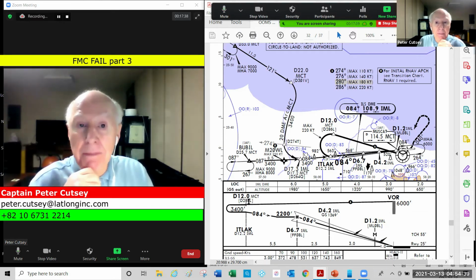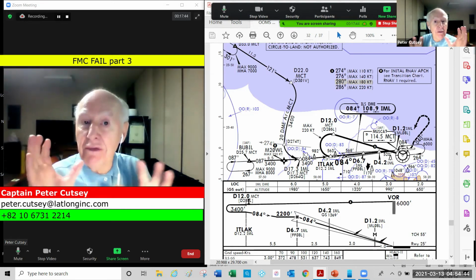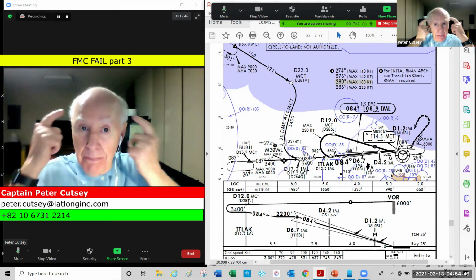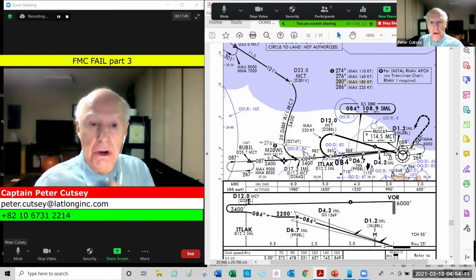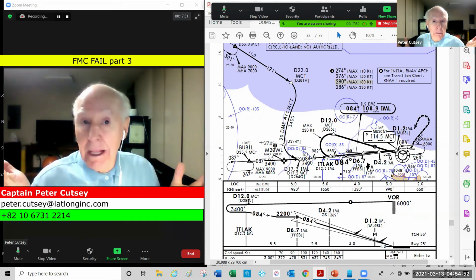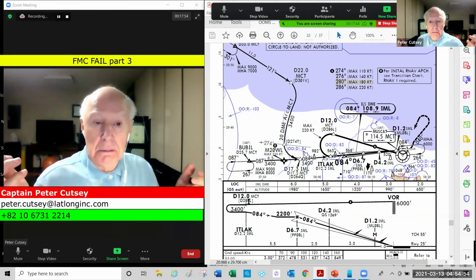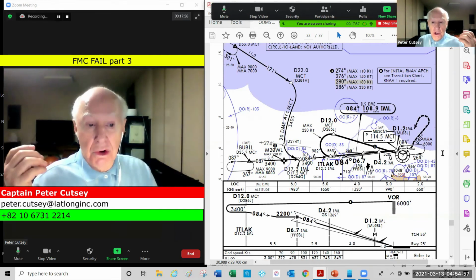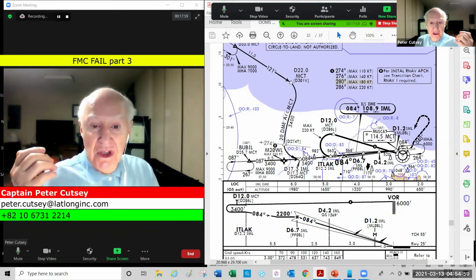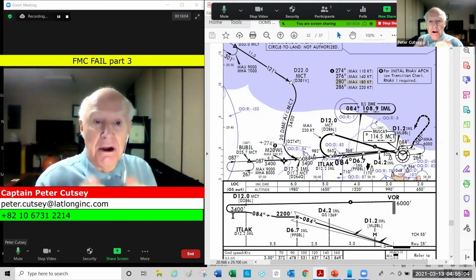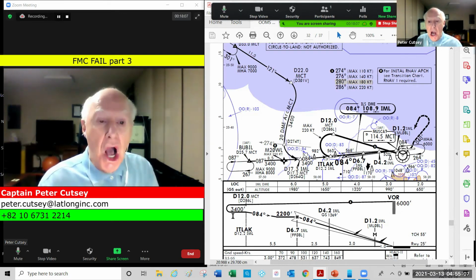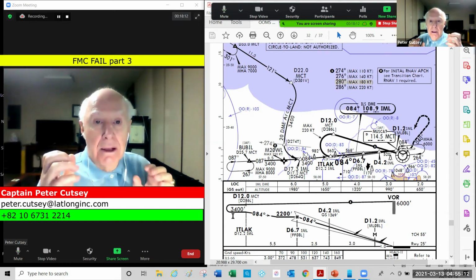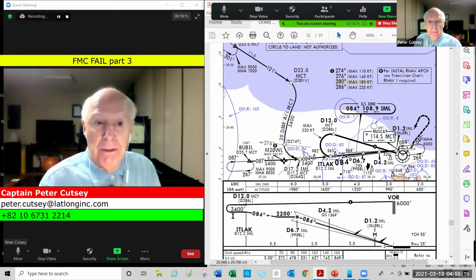Well, you've got all that information on your nav display. Remember, I showed you that before. All that great information. You don't have a map. The map is here, but you've got the DME. So you're going to go to 12 DME. You're using the autopilot, and you're using vertical speed. A good suggestion. And you're going to lose from 6,000 feet to 3,400 feet. You've got 12 miles to do it. You've got a vertical speed arc. Use all the data that you've got so that you can actually have a constant descent path.